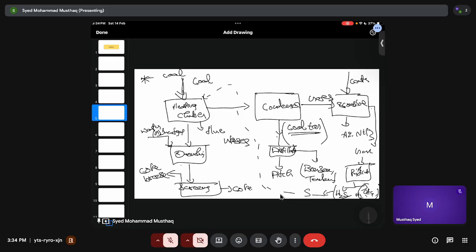Whatever gases remain after cooling, you separate ammonia out using a scrubber by adding water. After that, finally you will have all the gases, and in those gases you can have hydrogen sulfide and hydrocarbons that can again be separated.